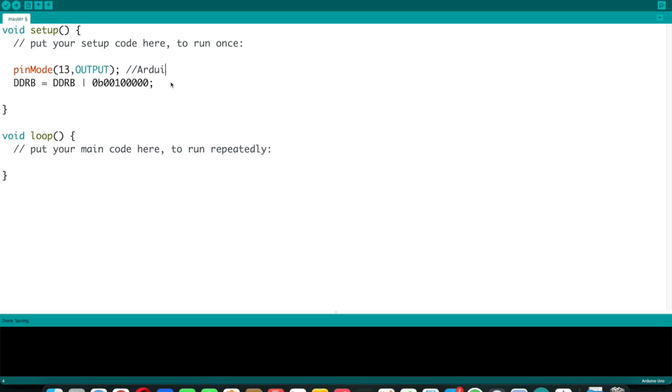This is Arduino C, and here this is embedded C. And actually on Arduino C, you can write embedded C. But there are definitely higher level functions like the pin mode that make your life easier, because you do not need to know actually which port and which pin inside the port the particular physical pin on the Arduino Uno maps to. I do not know pin 13 maps to which port unless I open the documentation.